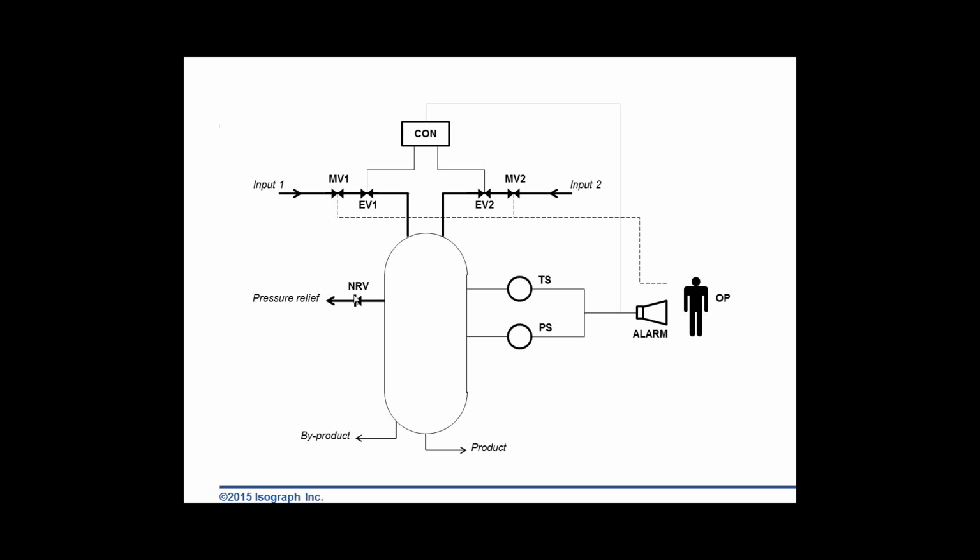We have a fail-safe, a pressure relief valve that will vent the excess pressure in the reactor, which will be a minor release of toxic chemicals. Should our pressure relief valve be stuck closed, and the runaway reaction continues because one of the inputs remains open, then that will lead to a rupture of the reactor vessel with the consequence of a major release of toxic chemicals. So what we'll be exploring today is using the fault tree module within Reliability Workbench to model the hazard